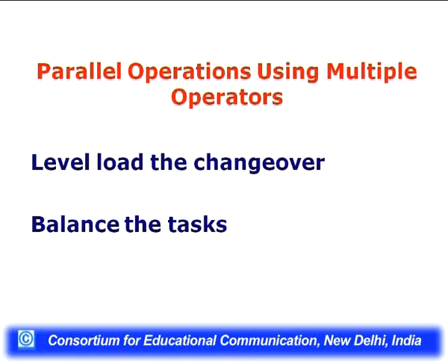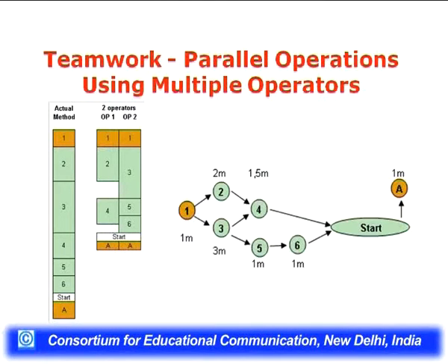This is the main principle of the changeover, because we have decided to do it simultaneously, and simultaneously at 2-3 locations the jobs will be carried out, and at 2-3 locations the job should be divided in such a way that they are balanced, means idle time on each point is 0, or negligible. Only then we shall be able to reduce the total setup time. This again diagram shows the teamwork, parallel operations using multiple operators. Multiple operators are used for carrying out different jobs simultaneously, so that the total time for setup and total time for changeover is reduced.